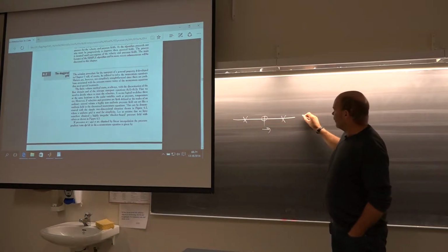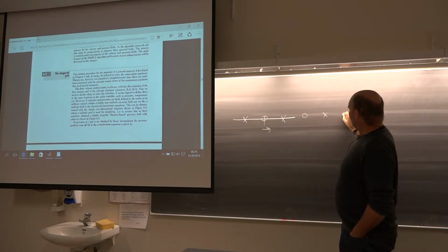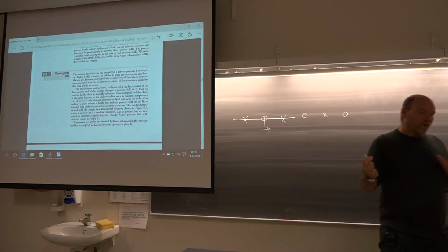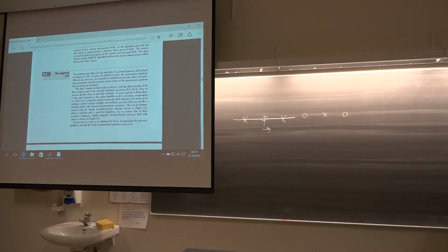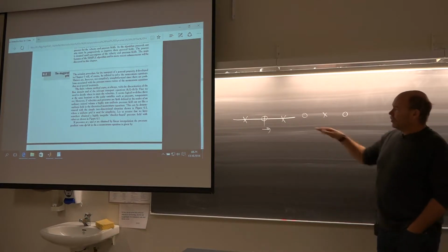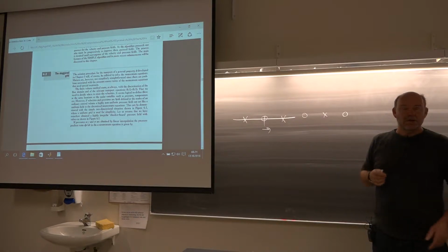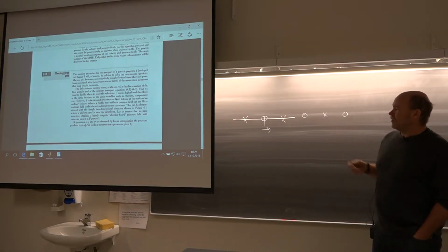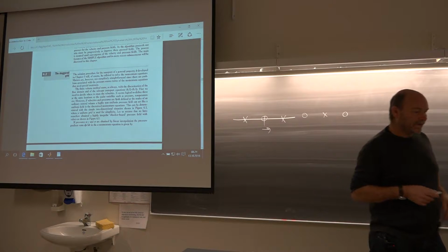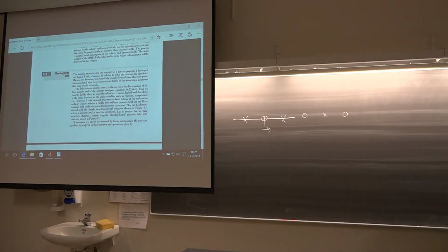So every other point will be one pressure solution, one pressure field, and the other ones then a completely different pressure field. And these two fields, they don't talk to each other at all. So that's the problem. You risk obtaining a checkerboard pattern when it comes to the pressure.